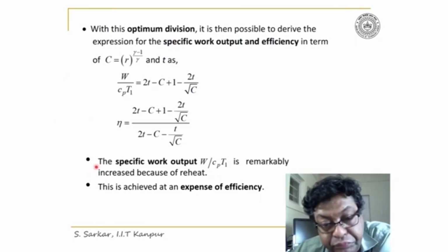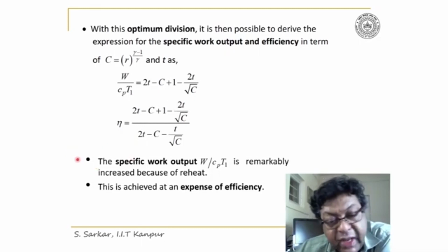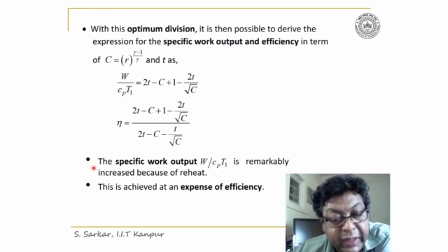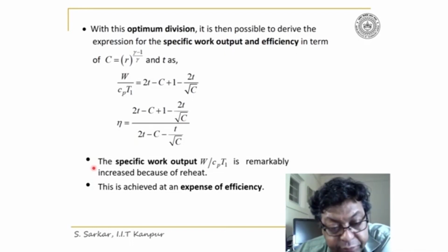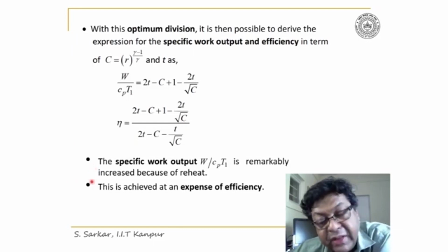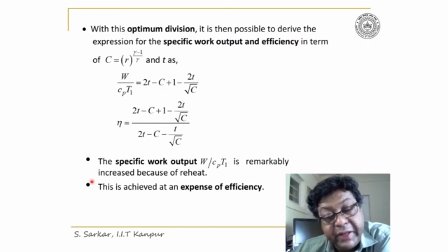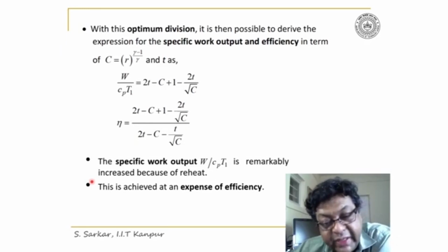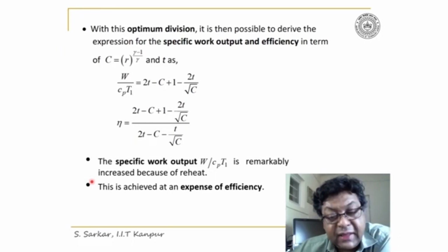Well, in conclusion, I can say that the specific work output is remarkably increased because of reheat, and this is achieved at the expense of efficiency. Thus, the efficiency of the reheat cycle will decrease, or will be less than the simple gas turbine cycle.